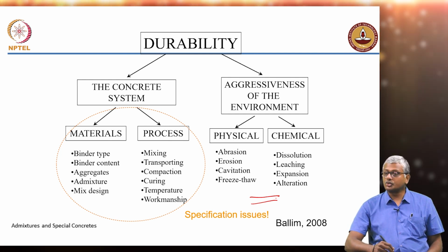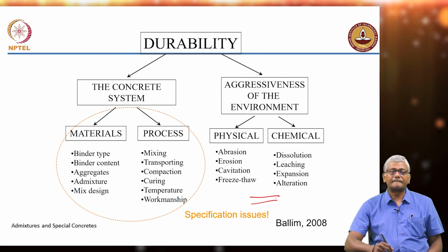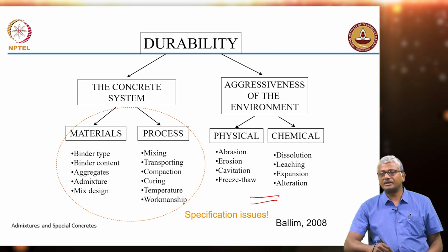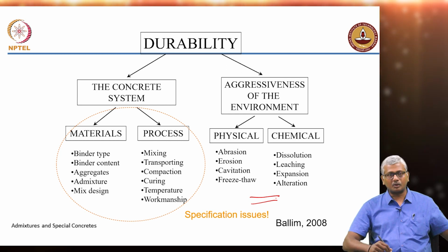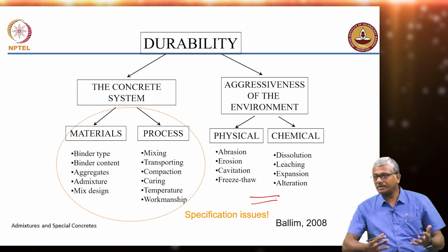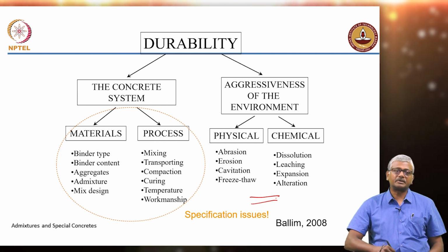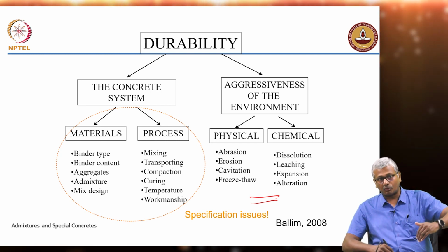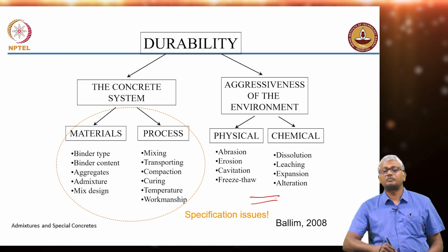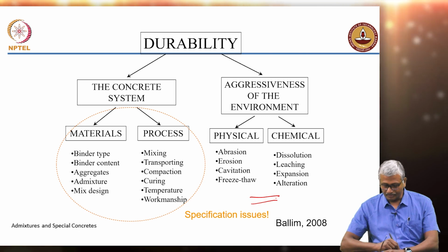What about erosion and cavitation? Dams, right, because when the river is in spate, it will carry huge rocks and boulders also along with it. So, all that goes over the spillway and falls on the concrete, and you really need to be worried about what is going to happen. Cavitation of course happens because of the drop of water and the bubbles that finally end up bursting, and that can create significant pressures that can damage your concrete.